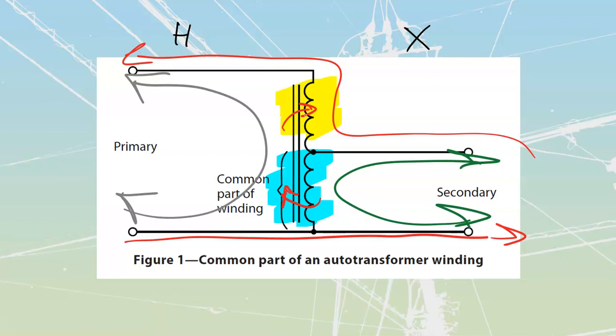Because we have shared windings, they're going to require less actual winding to make. There's going to be less copper associated with them. They're also going to have less steel for the core itself, which means that overall it's going to be a cheaper transformer to manufacture. It's going to be smaller because I don't have to completely isolate these things. And I'm going to have a higher efficiency because I have less core. As soon as I get less core, I've got less area for all of my stray losses: skin effect, hysteresis, radiation, eddy currents, and dielectric losses.